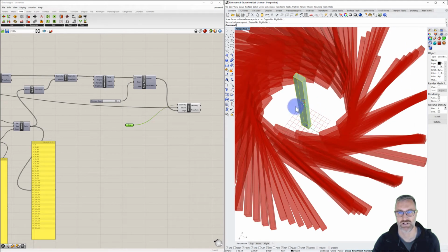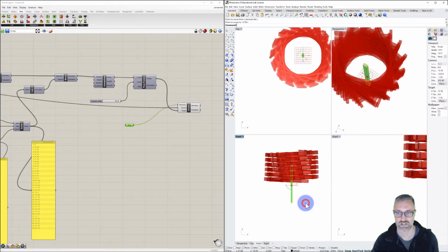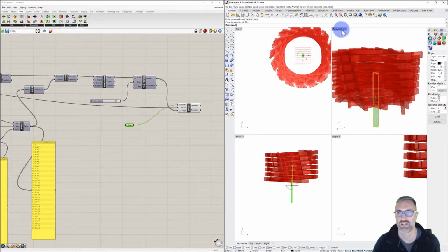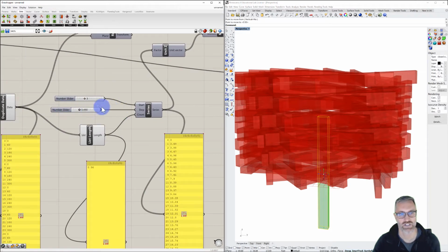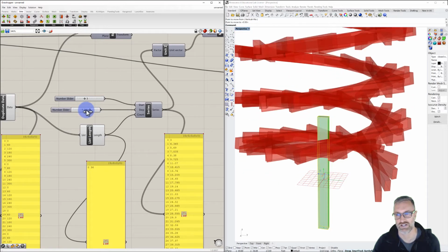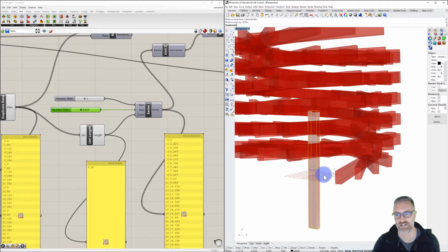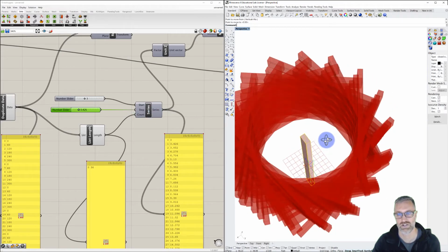If we want to move them down, we could do that. Maybe I'll go to the front view. Now we can see the way that they're beginning to approximate that space. Remember, we've got our unit Z, so we can always increase these or decrease these. We could probably even map. You could play with mapping the height of your step here and match it. So this B rep need not be a kind of simple geometry that we just draw in Rhino. That could also be tied to our variables, right? And so if we lower this down, we can start to produce some other things.